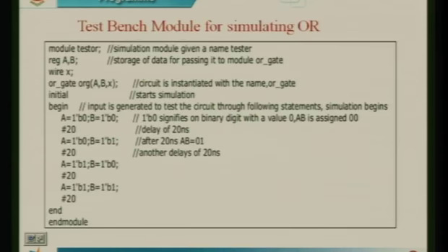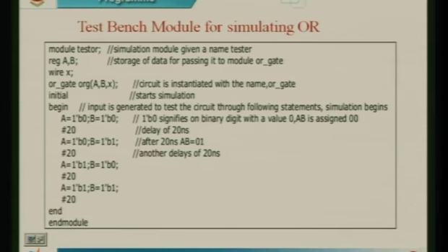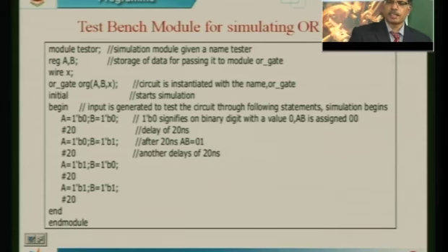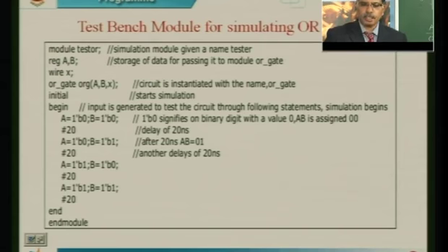Okay, this is a test bench. You can create a test bench for any model that you have written in terms of Verilog or VHDL, and you can simulate it to check the functionality of the model that you have written. If anything is wrong, go back to the program, change the syntax or instruction and correct it, and again re-simulate it by using this test bench model to check whether you are getting a proper output or not. Okay.